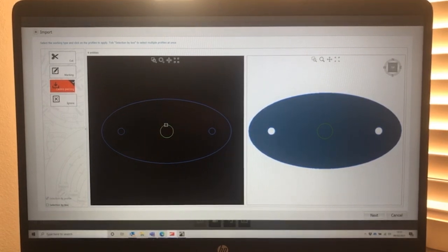So what you could do in this situation is, using the center pierce tool, select that center pierce again, and it goes darker over here on the right, and what it will do is, using the plasma itself, it will just pop a mark right in the center of where this hole will be on the component itself, just allowing you afterwards to line it up on a drill and then effectively just to pierce it out, and then you can cut from it from there.